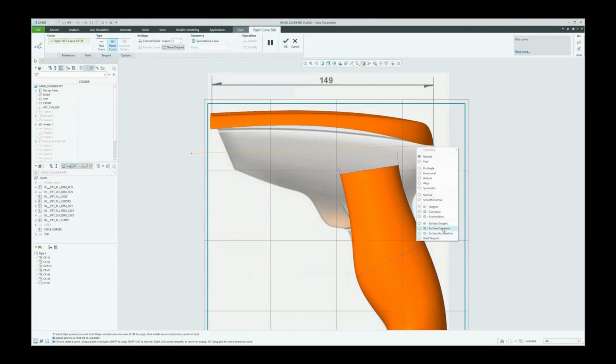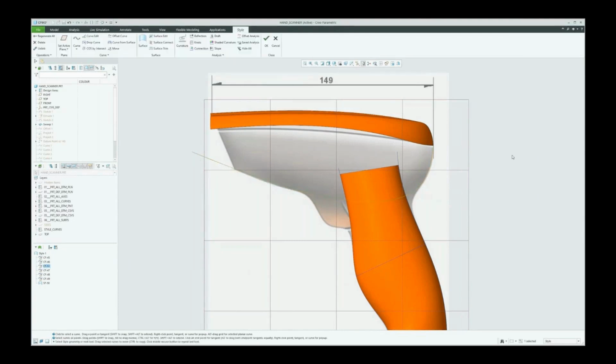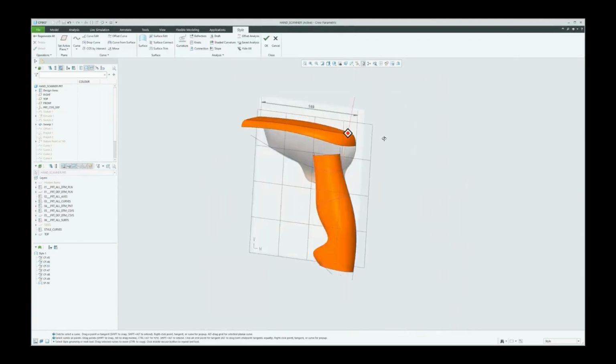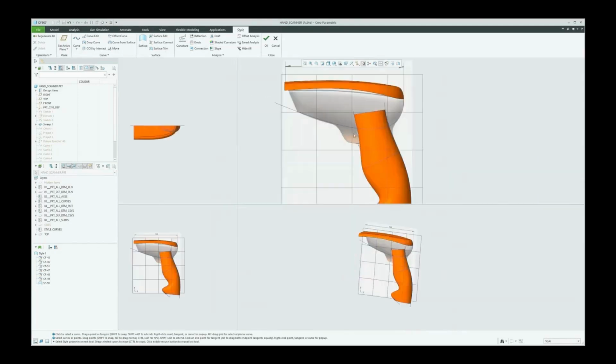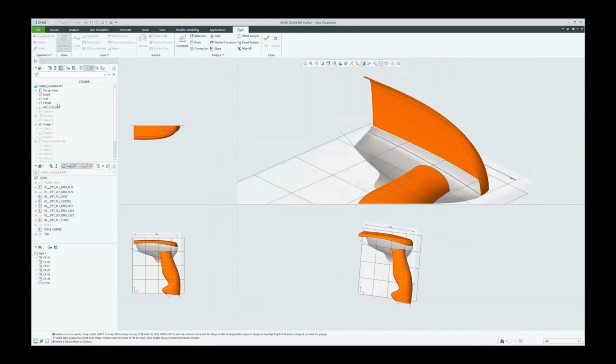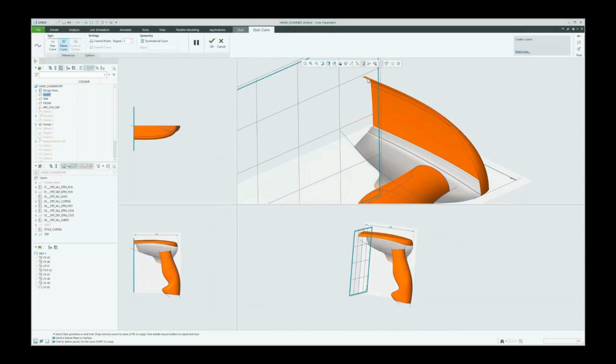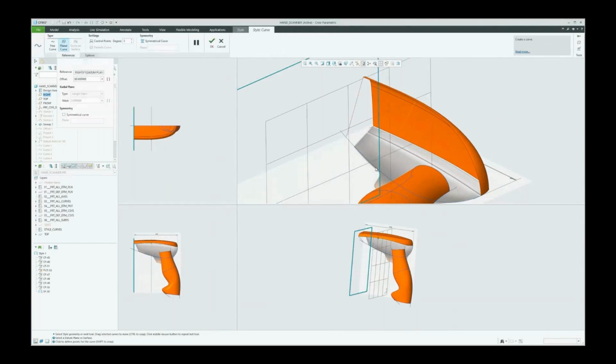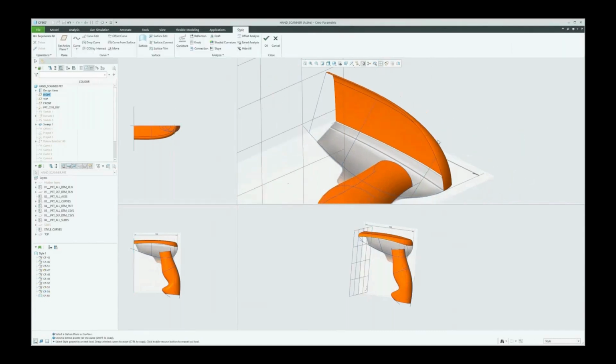So you get the best of both worlds, right? You get that creative freedom of these flowing shapes and advanced curves, but you also have that parametric control when and where you need it. We can link to parametric geometry, and we can build and tweak dimensions within ISDX as well when we need to. So the toolset is made for surfacing, and you've got G0 through to G3 continuity. So whether you're aligning edges or refining reflections on your model, ISDX has you covered in that state.